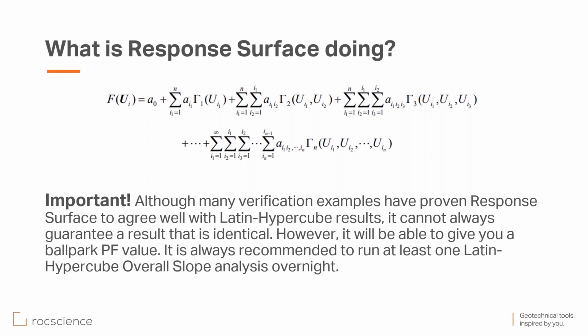But one thing that's important to note is that although we have done tons of verification examples and the results have been really good, still response surface is predicting the factor of safety. So we always recommend running an overall slope Latin hypercube analysis overnight.